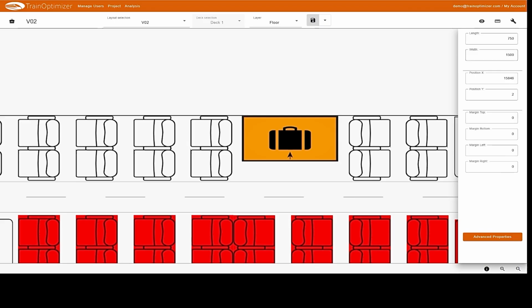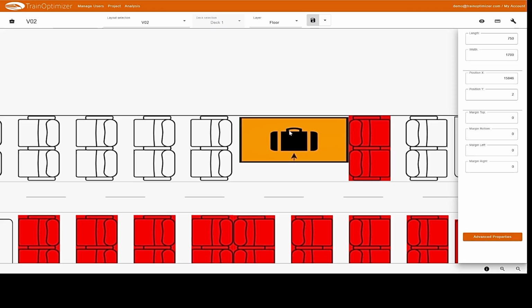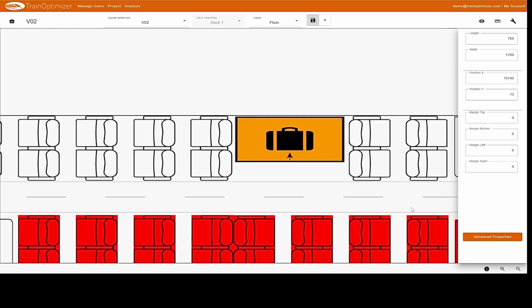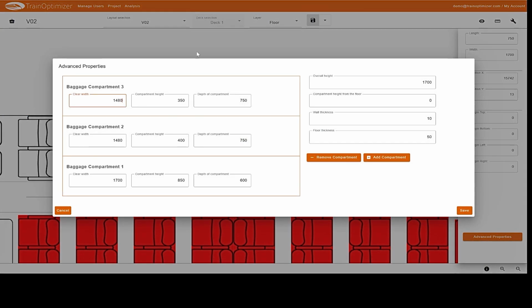We choose the increased distance of 1,700 millimeters, but we also have to adjust the change dimensions in the interior. In fact, 1,680 millimeters are available. At the bottom, there is a greater width due to the adjustment to the seat back lines.